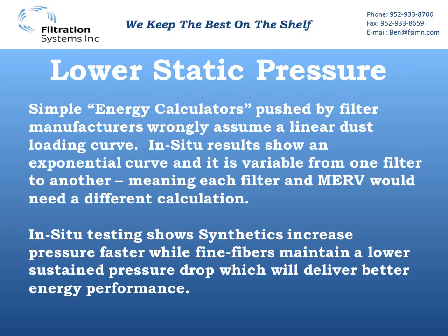Synthetics load much faster than fine fiber filters. They just get their air cut off much faster because of how the dust holds in the media, a lot due to the fact that synthetic medias have a lower dust holding capacity, and that dust holding capacity is all determined by how quickly the filter reaches final static pressure.